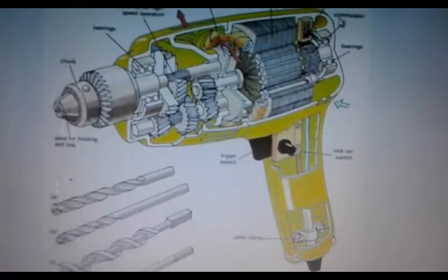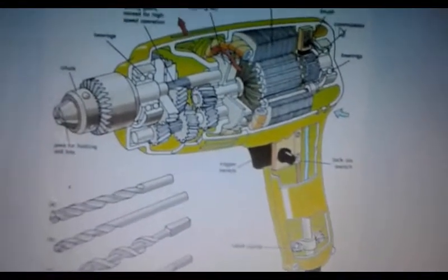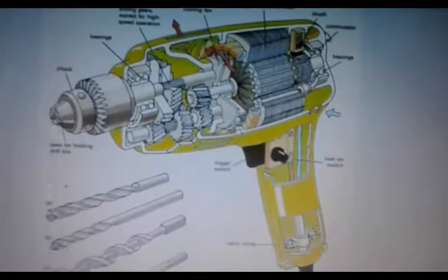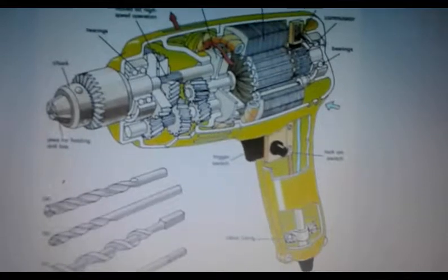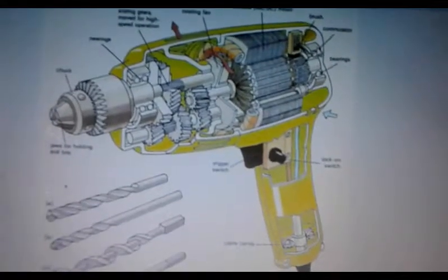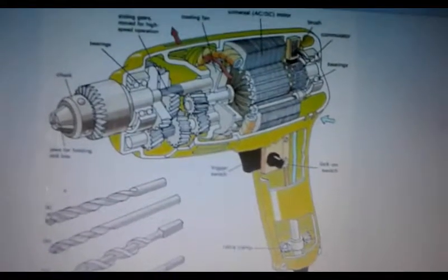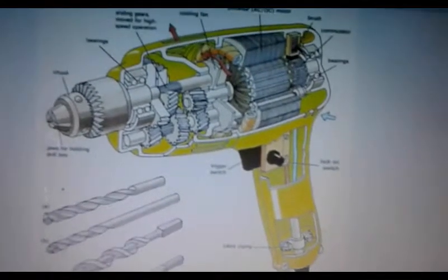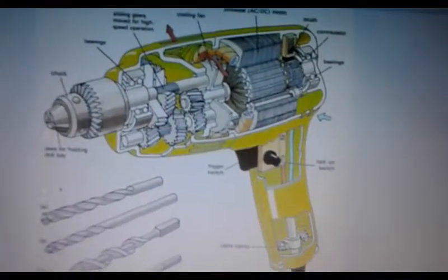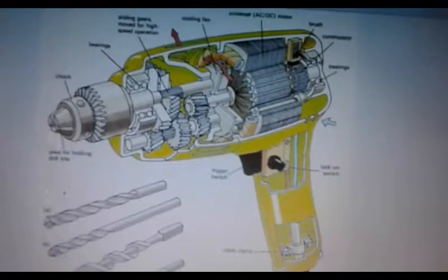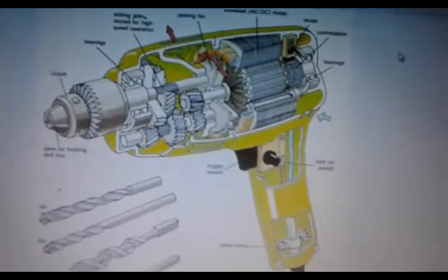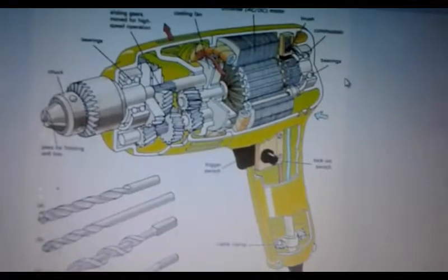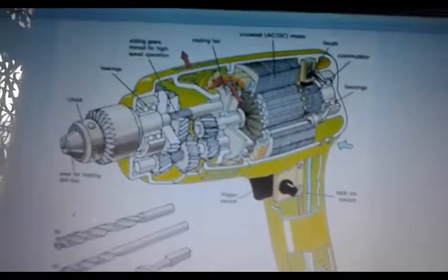Don't worry about the meaningless technical name. The slightly old-fashioned word commutation is a bit like the word commute. It simply means to change back and forth, in the same way that commute means to travel back and forth. In its simplest form, the commutator is a metal ring divided into two separate halves, and its job is to reverse the electric current in the coil. So each time the coil rotates through half a turn, one end of the coil is attached to each half of the commutator. So the electric current from the battery connects, described more easily here.